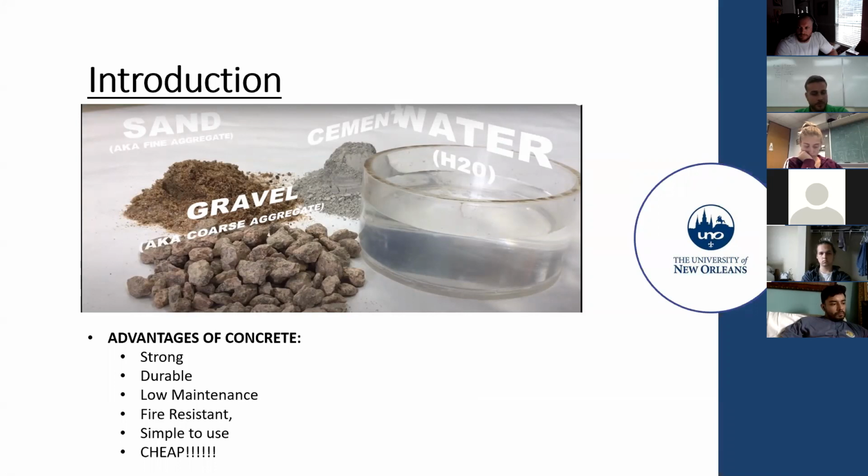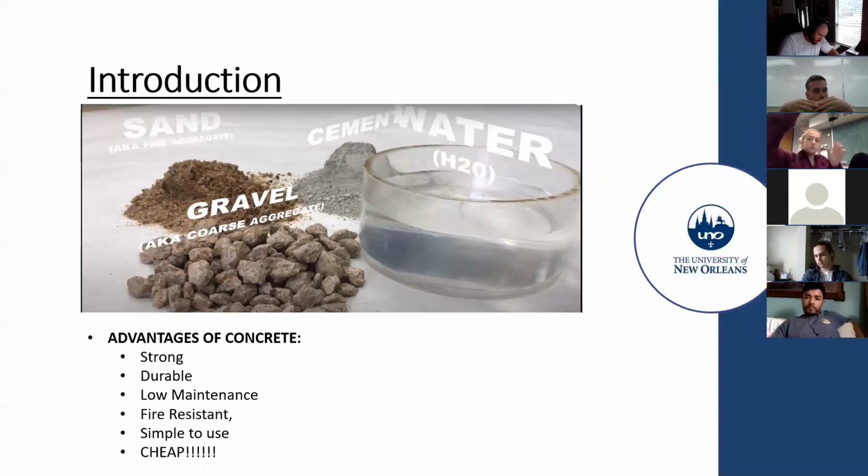Bradley? Okay, if you correctly understood what I said, this is the answer that you were expecting. I'm going to read one more time from my script. Portland cement cures not through drying or evaporation of the water, but through a chemical reaction called hydration. During this chemical reaction, heat is released, and we're trying to keep the temperature lower to avoid temperature increases because they cause additional problems.